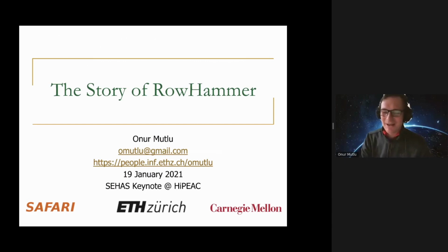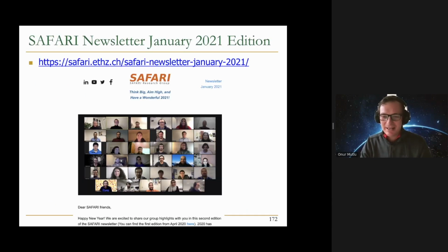That's a good question. Clearly, we have not got our hands on DDR5 and we have not done the studies, but we are in touch with people who develop them and actually expect them. In my perspective, it's going to be more vulnerable because it's going to be a newer technology node. Fundamentally, the vulnerability will be higher. Now, DDR5 introduces, in my opinion, an unnecessarily complex and difficult to understand way of handling Rowhammer bit flips. They call it RFM, refresh management.